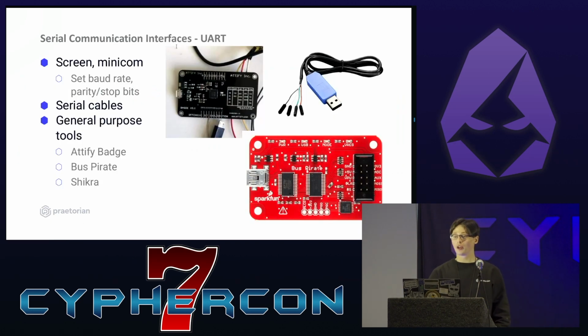So now we know where the pins are. We know what they do. How do we talk to it? A number of different general purpose kind of multi-tools. The Bus Pirate in red here is one of my favorites. So you can use that with a utility like Screen or Minicom, configure it appropriately with the right baud rate, parity and stop bits, and get talking to it.